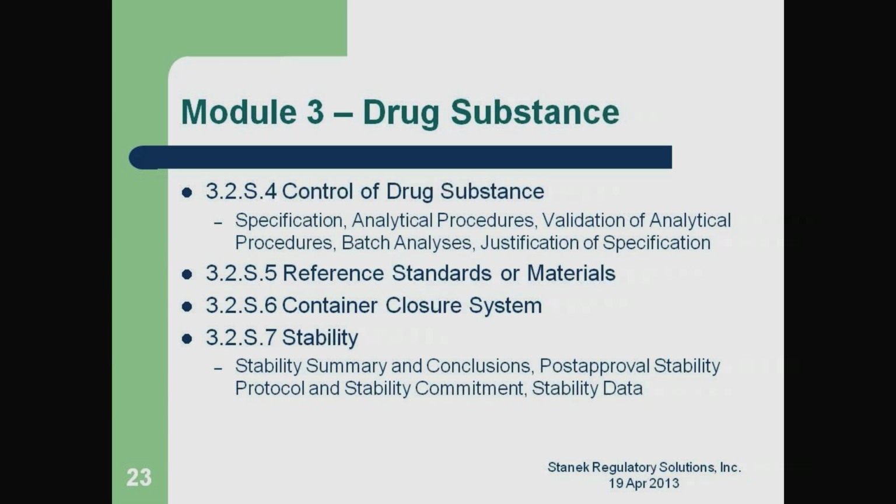Batch analysis is expected. Usually the rule of thumb is 3 batches. I've never seen it where you've needed 3 full-scale batches. These can be pilot scale. Certainly, and we'll get into this a little bit later, if you have some full-scale data, that gives you a lot more comfort with everything else you're committing to, and that the DMF is actually going to hold true when you scale up. And then your justification of specification.